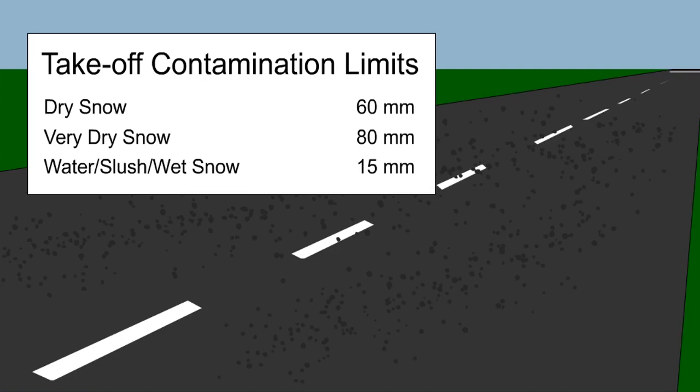However, takeoffs should not be attempted with a dry snow depth of more than 60 mm, or more than 80 mm of very dry snow, or in more than 15 mm of water, slush or wet snow.